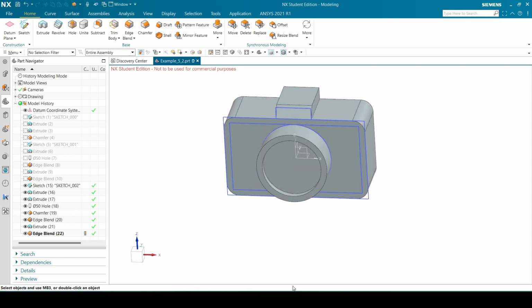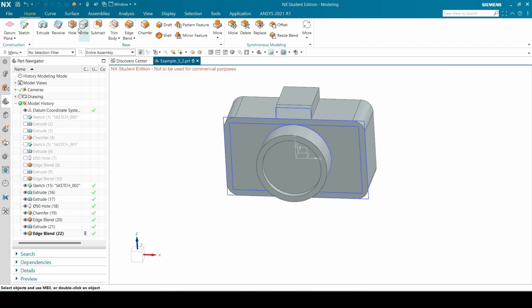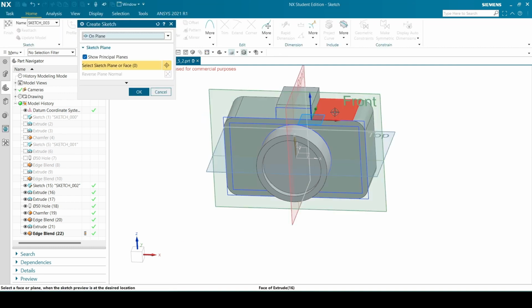Now all that's needed are those 2, that circle and that little square. So you can technically create a sketch on one of these faces and draw on it, but I'd rather not do that in case you changed one of the extrudes or deleted it or suppressed it, and then the sketch that works from that face is not going to work anymore. It's going to give errors and stuff. So rather use one of the front or the top or the right plane.